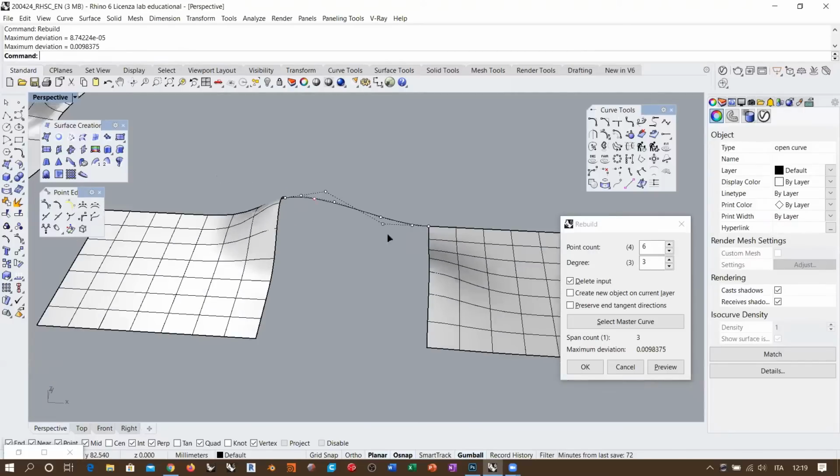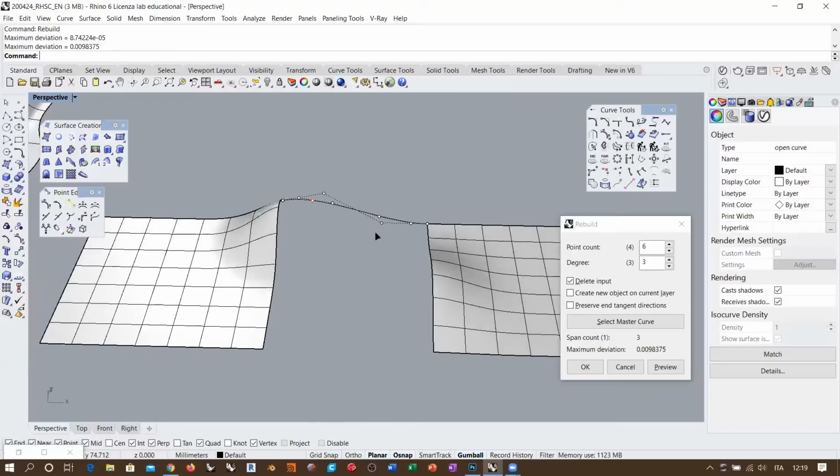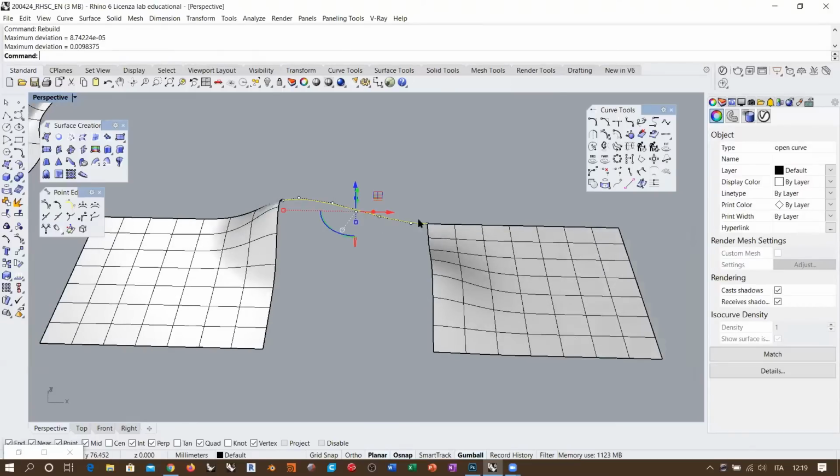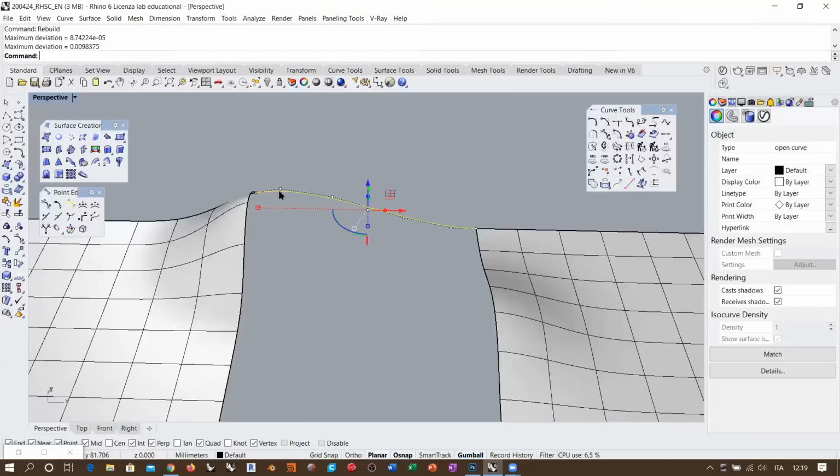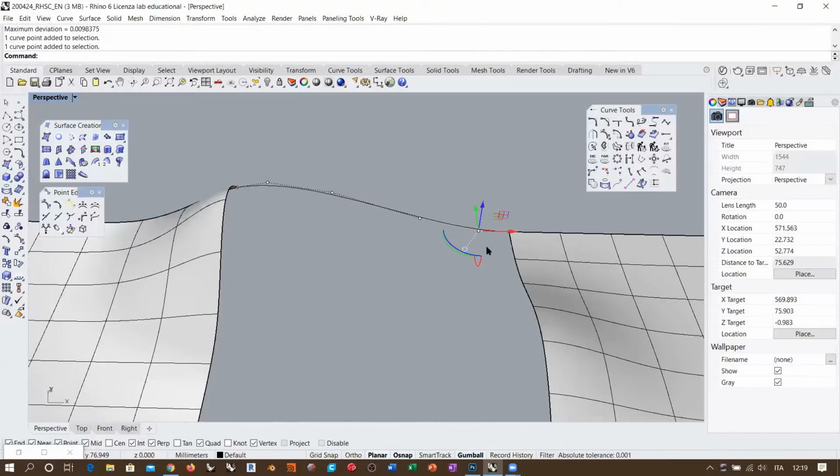So if I rebuild this outside from the sweep to rail, I am creating the right topology, but not the right continuity, because I still have tangency and tangency, okay? Because I have basically almost didn't touch the geometric aspect because the maximum deviation was very small, okay?